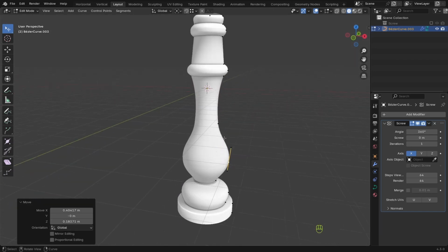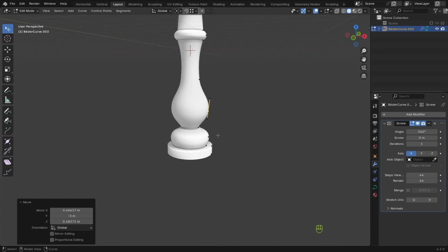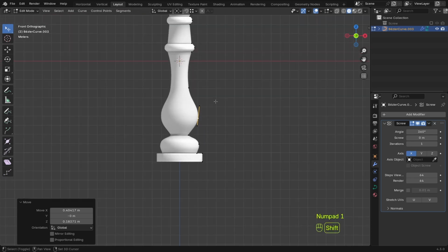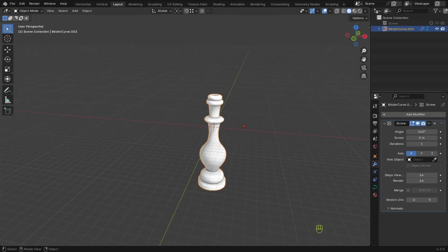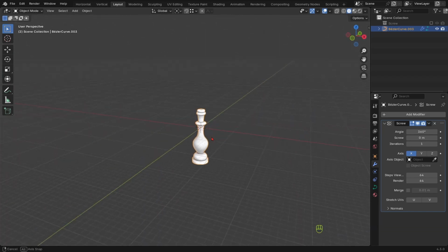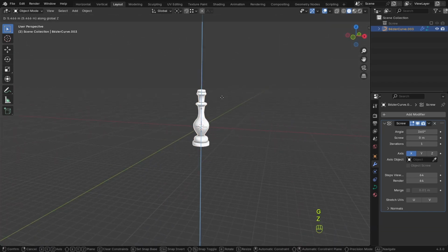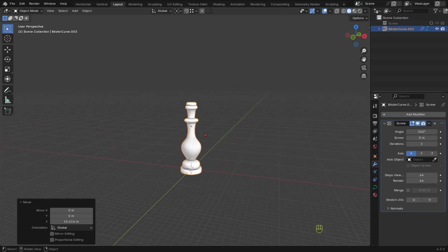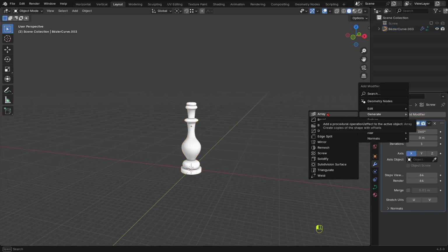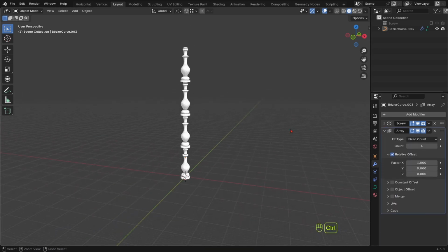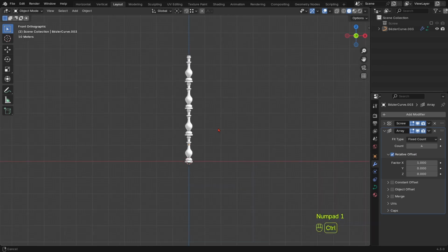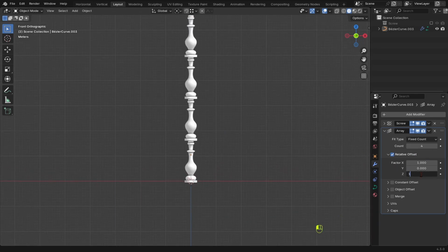So this is some interesting shape that we have created so far. We could work with these more to create even better shapes. So that's what we have created so far, and let's use another modifier to make our job faster, instead of just taking duplications of these, and that's going to be the array modifier. With the help of array, we can stack these objects a couple of times without duplicating them. So let's play around with the Z instead, set it to 1 and make it 0.